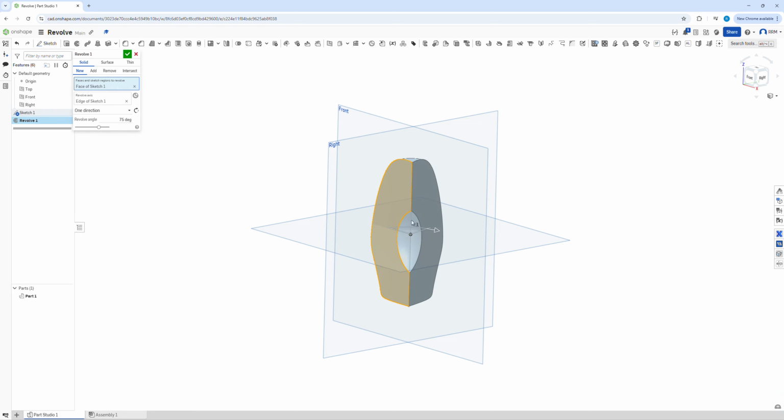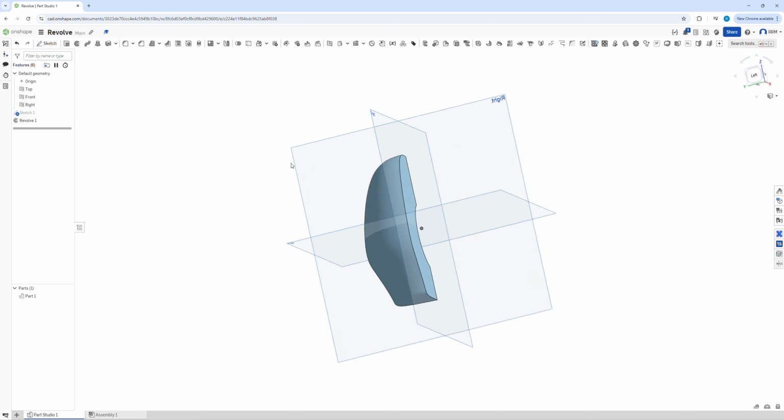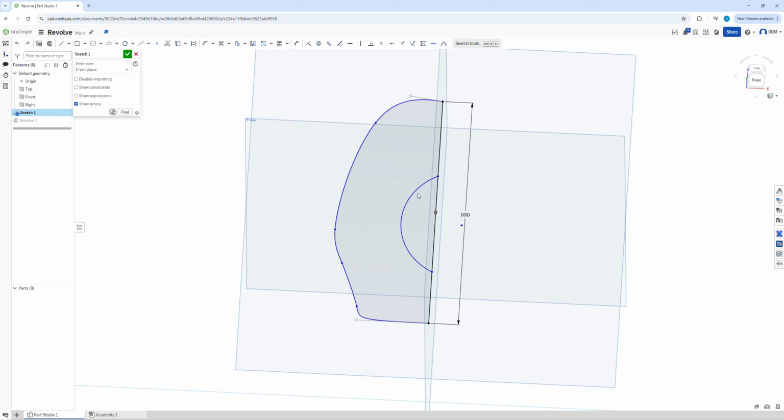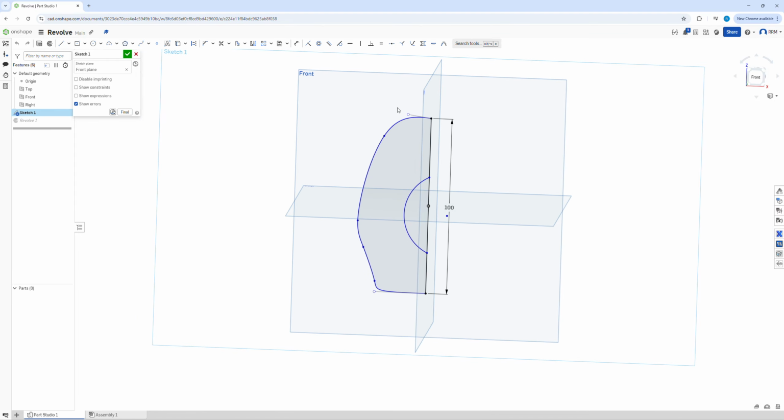You need to make sure that you've got the selected part, and then you are finished with a revolve of that part. Why is this blue? This is blue because I did not dimension these parts here, okay, which is quite useful. When you're dimensioning a spline, it's very complex to dimension it. It takes a bit of time, basically.